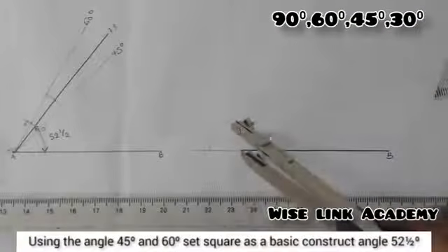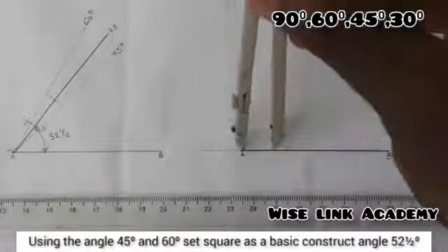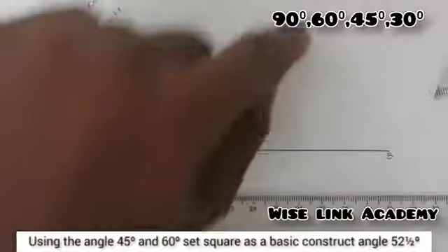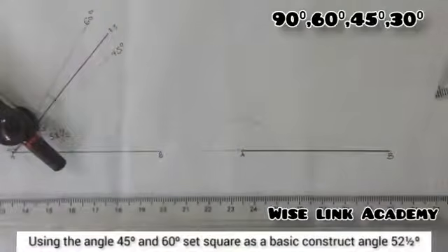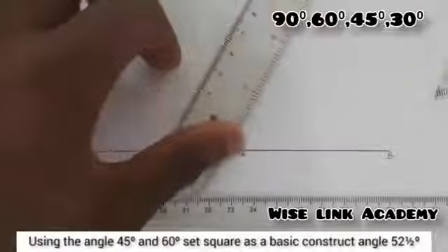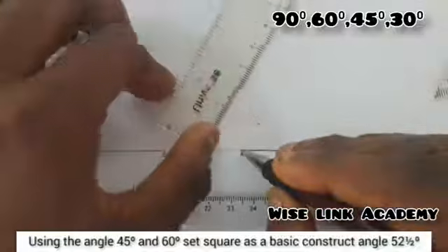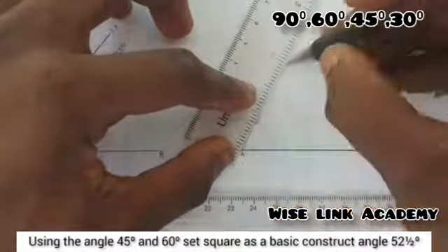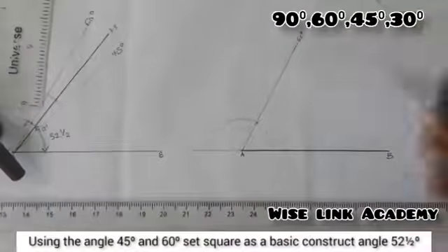I have it. My next task now is to take the measurement from this point to this point. As you can see, strike an arc. Automatically, if I draw a line connecting them, what is it? Angle of 60. So I'll take my meter rule and draw a straight line connecting those two points, this point here and this point A, the center, with a faint line. Why? Because I do not need that angle. This is angle 60 degrees.